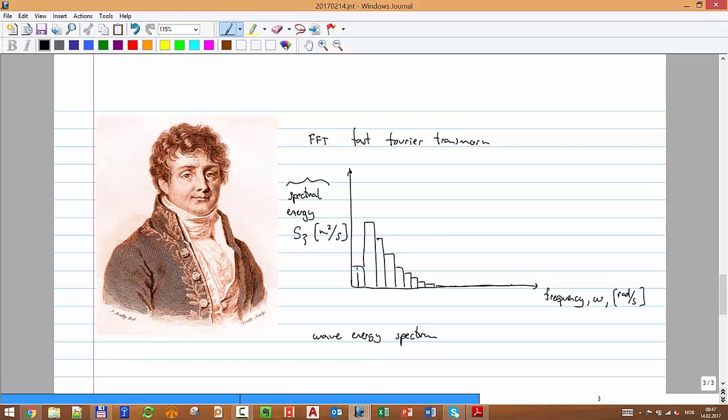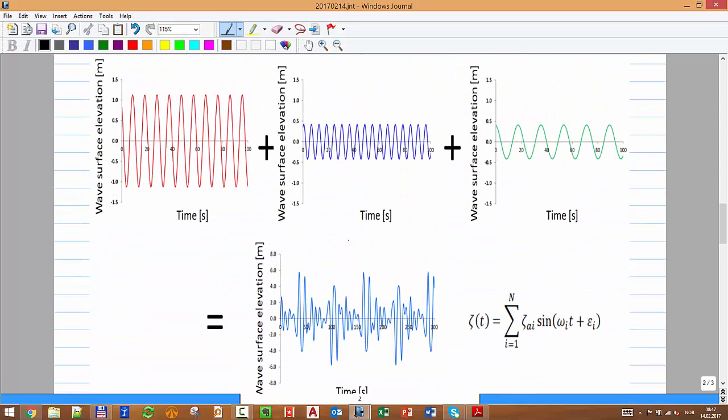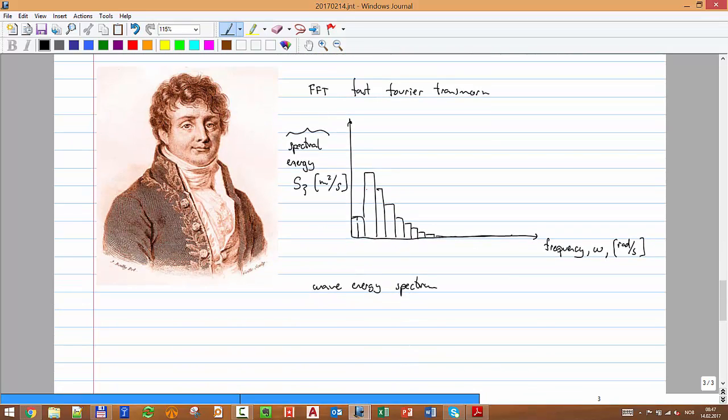So you have one frequency associated and the amplitude associated, and that is a way to describe your signal. That very complicated signal that you think doesn't have any trend, is not cyclic, I can describe exactly by this particular spectrum.